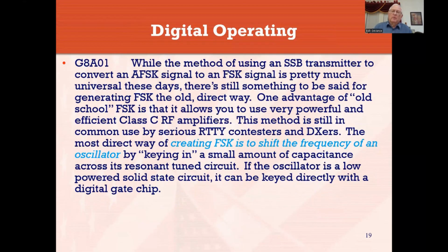Okay, the method of using a single sideband transmitter to convert an audio frequency shift signal to a frequency shift keying signal, rather, is pretty much universal. But basically, they're saying if it works, don't mess with it. It's the old direct way of doing it. One advantage of the old school FSK is that it allows us to use a very powerful, efficient Class C amplifier.